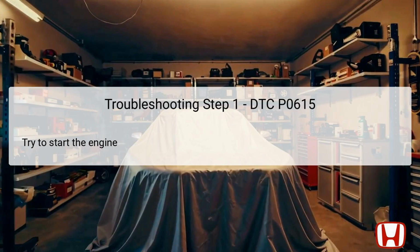The first troubleshooting step for diagnosing DTC P0615 is to try to start the engine. This initial test serves to confirm the existence of the issue and helps in determining whether the starting system is functioning properly or completely non-responsive. During this procedure, the technician should observe if there is any cranking sound or dashboard indication during the attempt. This step is fundamental in forming a baseline understanding of the current state of the starting system.